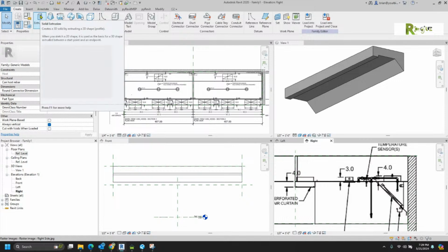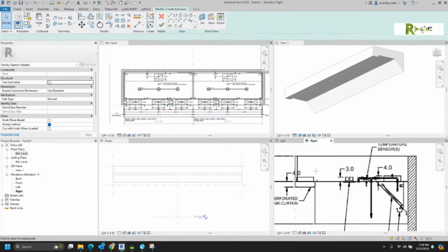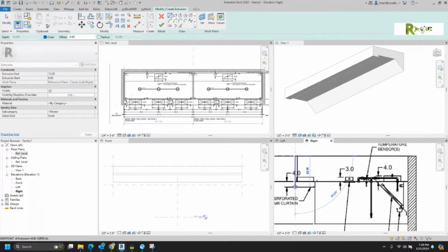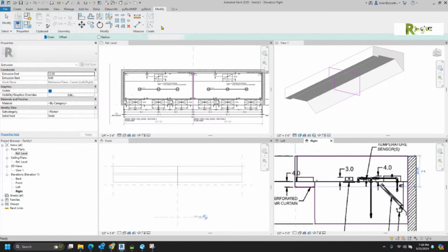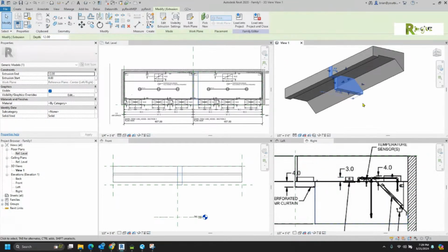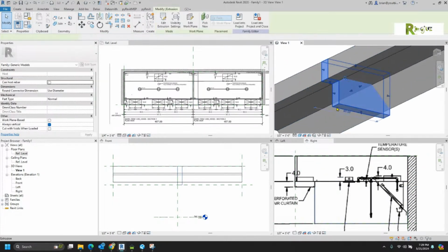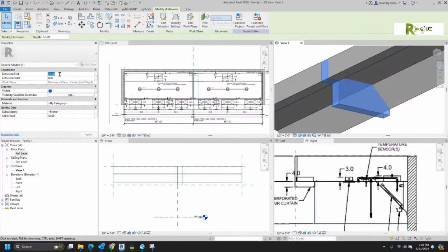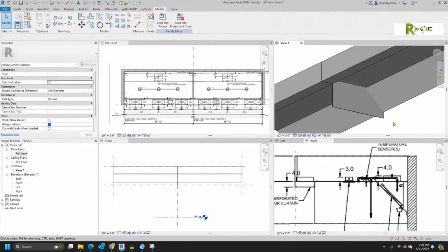So the one piece of the hood that we did not build is, and hopefully this will be a good lesson for even you, Misty, if I made an extrusion out here at the end, it's this end plate that sort of closes the end of the unit. So if I say finish, the first problem I have is this is only probably 1/8 of an inch. I'd always recommend never drawing anything as thin as 1/8 of an inch. So I'm drawing it 1/4 of an inch. It's just this thin piece at the end.